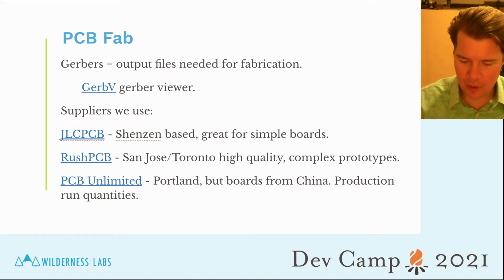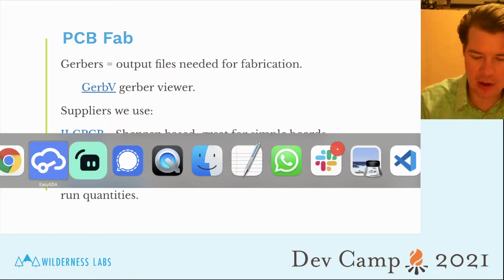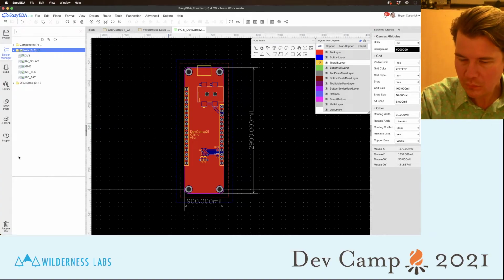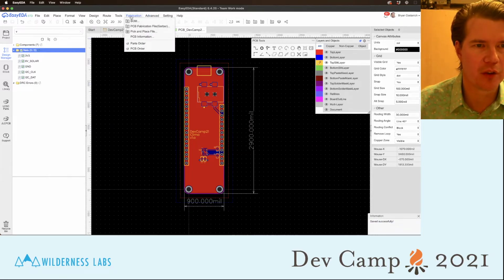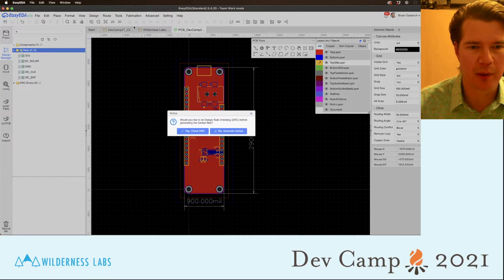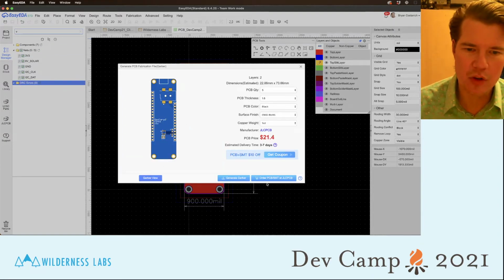The first thing that I want to show, and this is a nice thing about EasyEDA, is that if you're in EasyEDA, you can order your PCB directly from here. If you go to fabrication, PCB fabrication, check DRC, there's no errors, and you can order directly at JLCPCB from here.